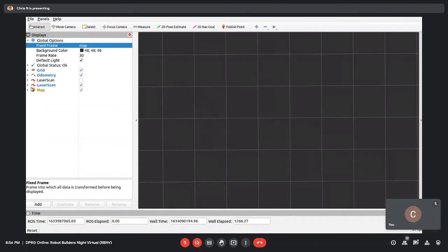And what I mean by playing back the data, so I was running my robot around my office and down the hall and recording everything, every single data point: odometry at 100 hertz, IMU at 100 hertz, the laser scan at 15 hertz, what else? Battery information. Whatever I'm generating, all these pieces of information at rates up to 100 hertz, it's all going into a log file.